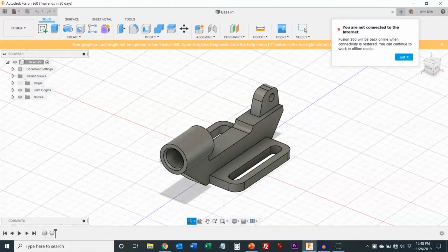This type of part would require what's called side actions. Instead of a simple pull mold, you now have these side actions that come in and help fill in these parts here. Let's say you wanted to make this part. The mold would also, in addition to the top and the bottom that pull out, have these side actions. A piece of the mold would come in and fill this hole here, so plastic doesn't enter there. And then you would have another side action that would slide into this hole to keep this hole from filling with plastic and therefore form the hole.